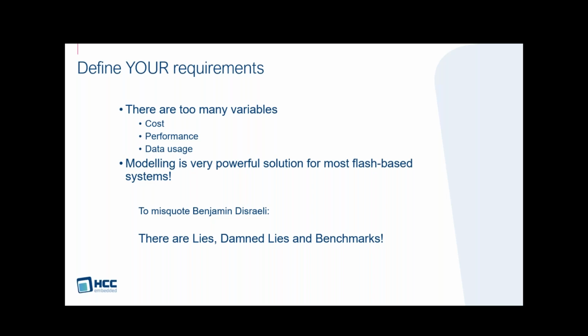Another very important thing about this is that flash is relatively easy to model. If you know what your project is going to be doing, if you know how you're going to be writing data over the next 15 years, then you can model that and see how the flash gets worn, what the speed of it is going to be at various points in time. All these things are very reasonable to analyze. I won't say easy, but certainly not difficult to analyze exactly the type of behavior you will get from your flash based on your application.